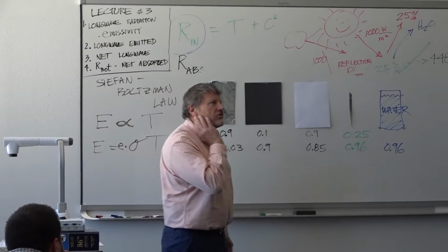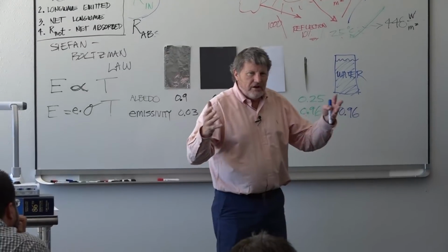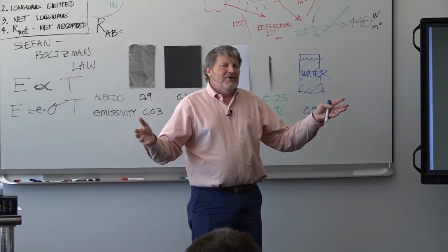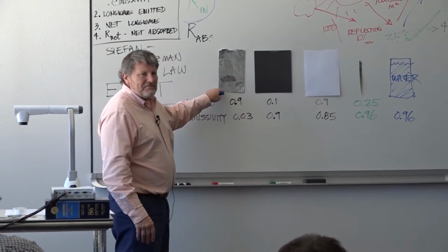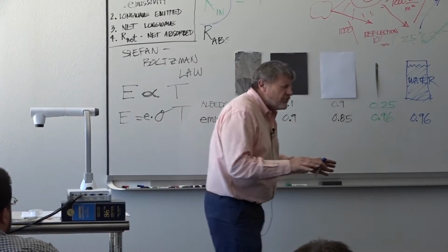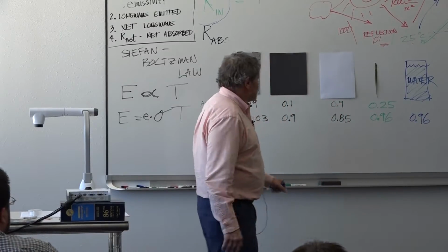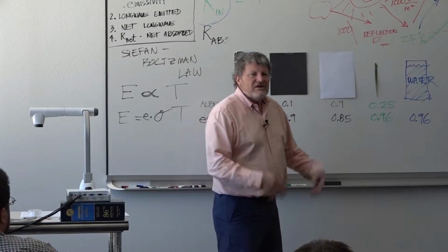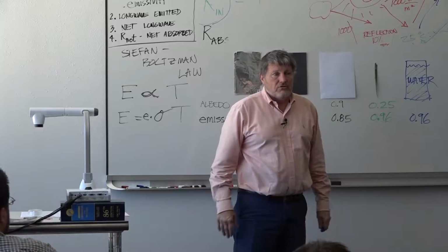So there's the concept of emissivity. And one of the things that I think of when I'm thinking about this is if we're designing wood stoves to heat the cabin somewhere, we would not want to build the wood stove out of aluminum foil. It'd be terrible. It'd sit there and get hot, and if you walked into the room and tried to find that wood stove, you wouldn't tell where it is. But wood stoves are black, and they're effective emitters. So as soon as a wood stove gets hot, it's giving off its heat to the room.